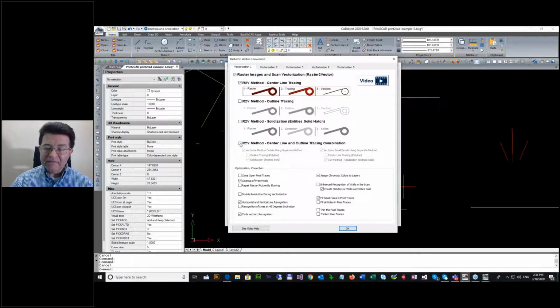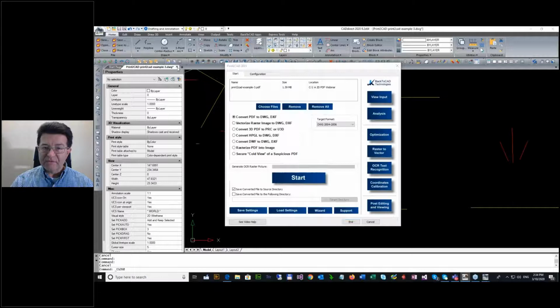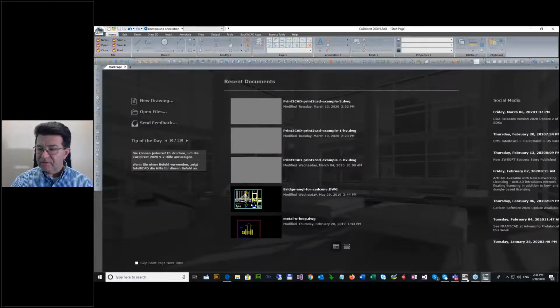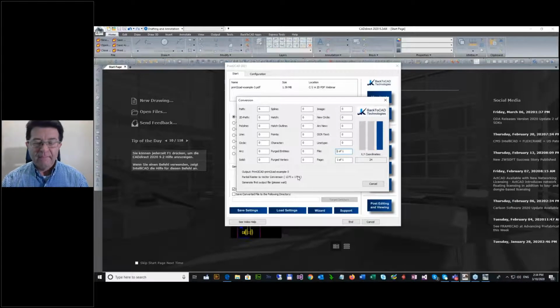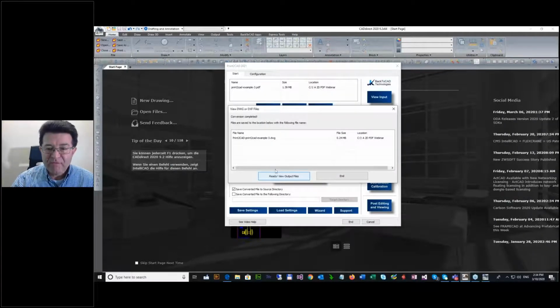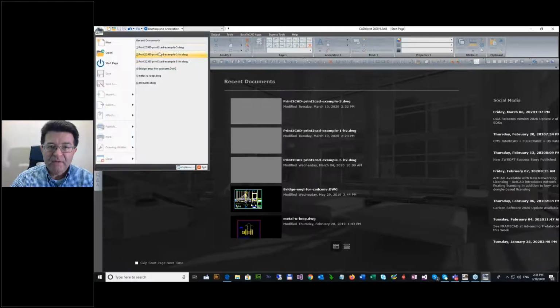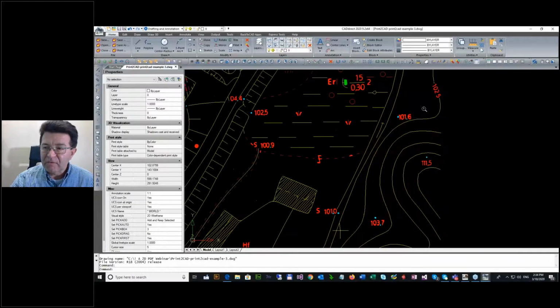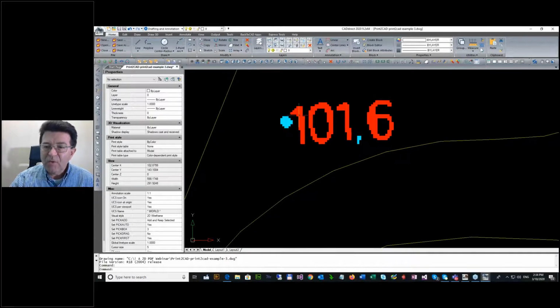Look, that was raster to vector, centerline tracing for the wall drawing. Now I activate again this method: centerline tracing combination and outline combination, and for small pixel traces, like these small symbols here, I use solidization. Let me do it now with these settings. Okay, you will see this is the reason that these settings are our default settings, because they are really perfect for bad quality scans. Because the text looks very similar. If you vectorize this text, you can't really read it. Now look what happened. Can you see it? It looks more like 101.6. We do not vectorize it.